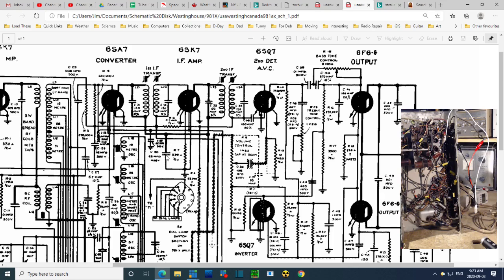Great. If it was leaky, you know what? You're trying to put B plus through the coil here, the DC, B plus onto plates. So there's a large voltage here, and that's why they darkened or heavied up this line to indicate that. In fact, any capacitor with a heavy black line coming to one side is under stress. That's interesting. Like this one, which I will have changed.